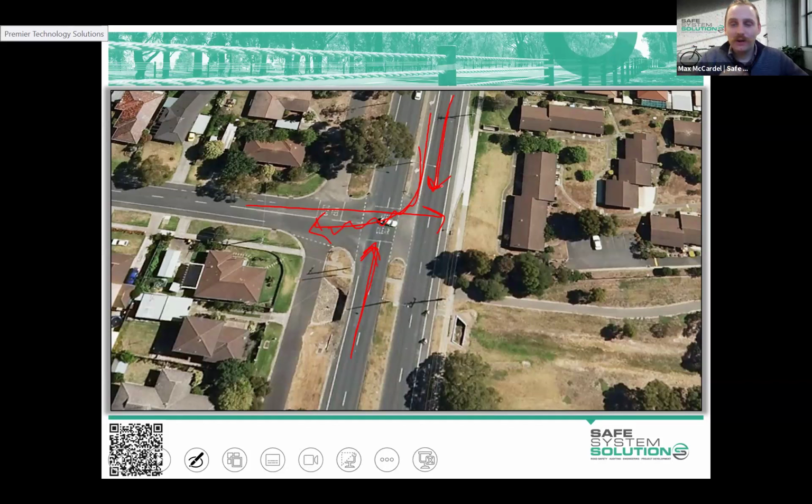The other thing to note about this specific area, just to help with your understanding of the characteristics of this environment, there's a bus bay here. So heavy vehicles run along here, buses quite frequently. I think it's about 12% heavy vehicle population on this north-south arterial. There's a shared use path on this side. It doesn't really connect very well across.